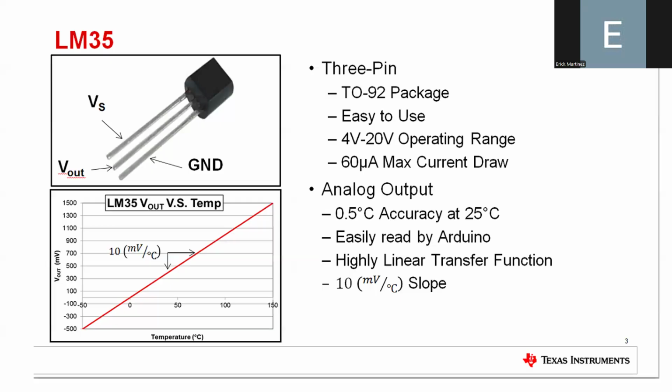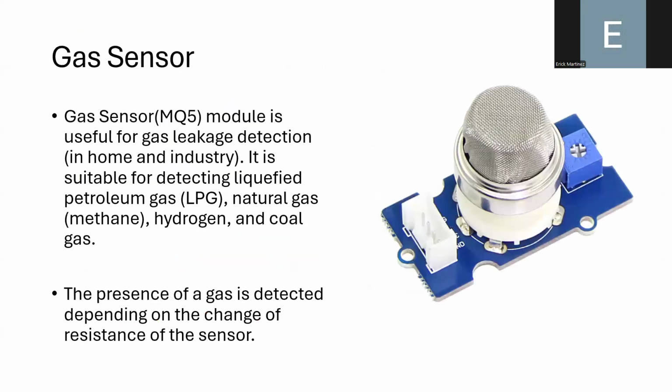And the problem is that, well, if you compare this sensor to thermocouples or thermistors, the sensor is a little bit more costly, but it's not too costly. You can buy it in any electronic store, and you can perform temperature readings very easily. And also you can integrate this sensor very easily with a prototyping board like Arduino.